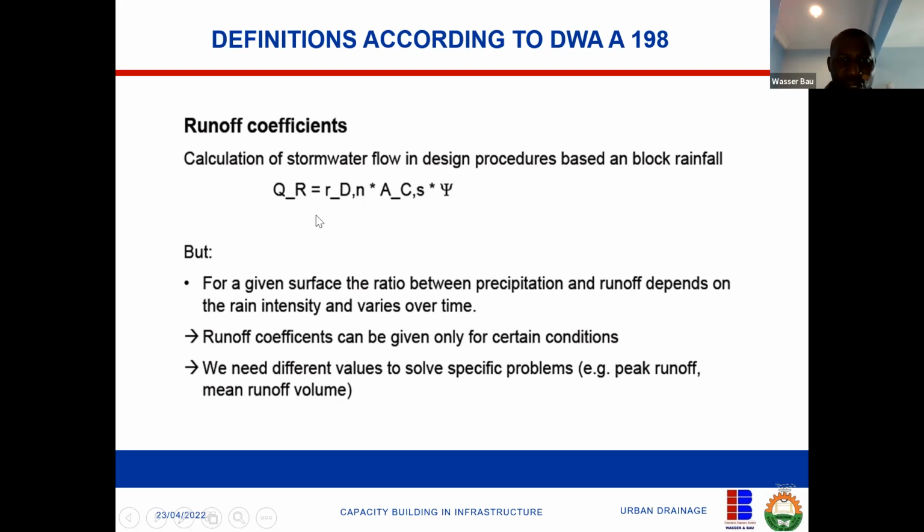So all these things you see here, I want you to see it as CIA. Where is the C? This is the C. Where is the A? This is the A. This C and S simply means catchment area, sub-catchment. Because when you want to get the total runoff, you will get it based on catchment 1, catchment 2. Okay, so this is like area of catchment sub.